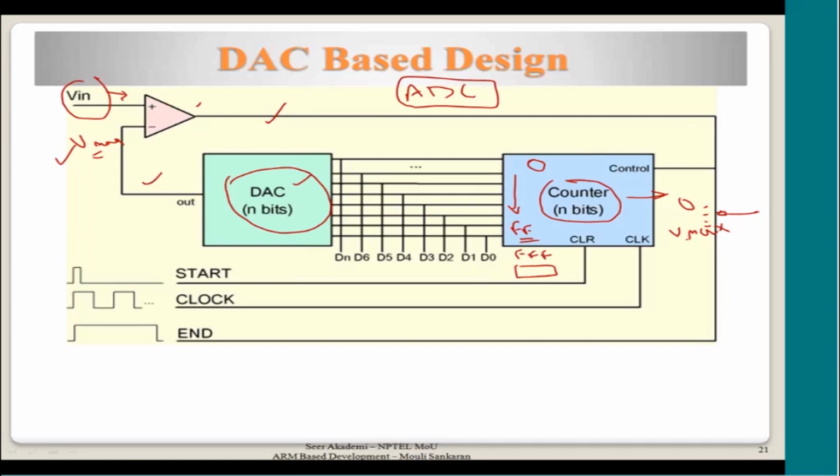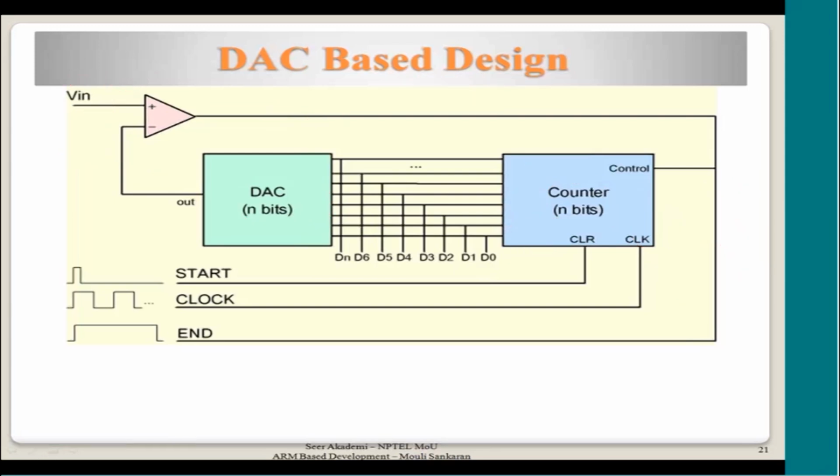It will go from one value to the other, and each of these values will correspond to some voltage from 0 to V max, split exactly into equal parts. Whichever voltage comes across that happens to be the same as the current input voltage, the counter is stopped, and the counter value will be the converted decimal representation of the input signal. I hope this is clear.